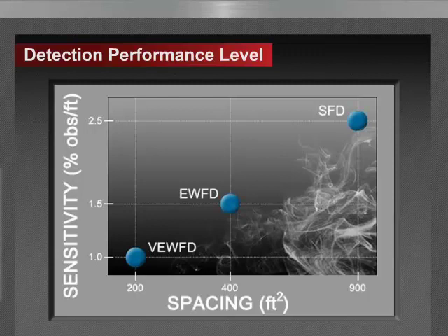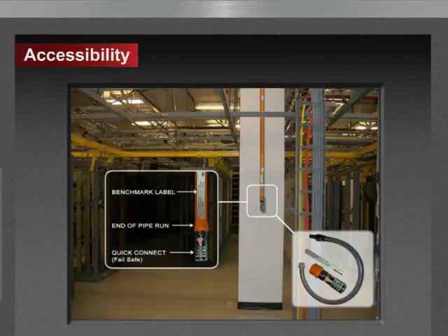So a question has to do with inspection, testing, and maintenance. Attendee asks, how and when should the sampling pipe be cleaned or serviced? That depends on the environment, and in most IT and communication infrastructures, you very rarely see that the pipe needs to be cleaned. But there are provisions, in the event that you do need to clean the pipe, and there are some monitoring points within the system that monitor and supervise for flow.